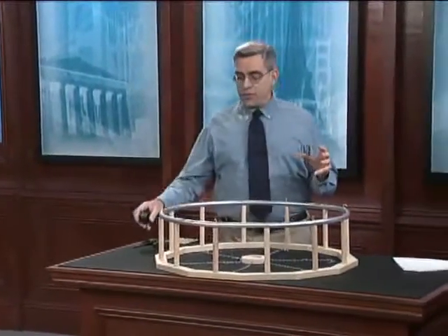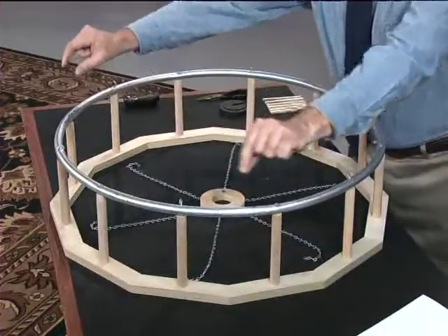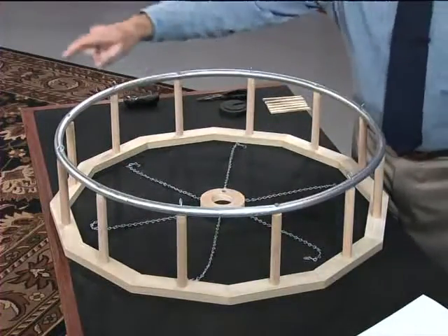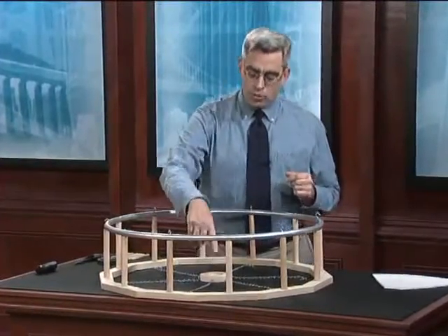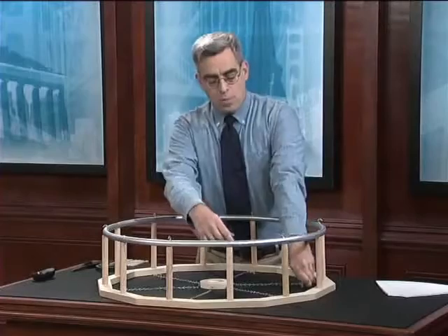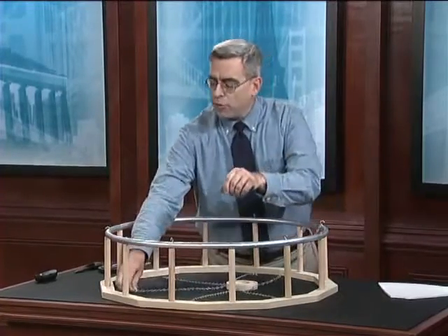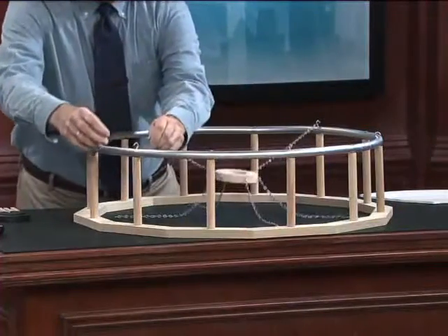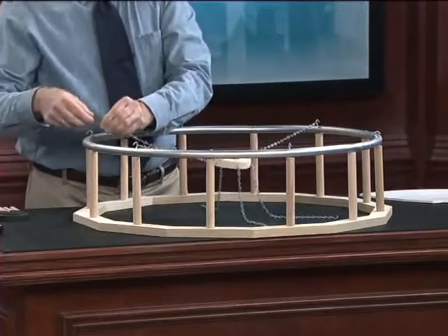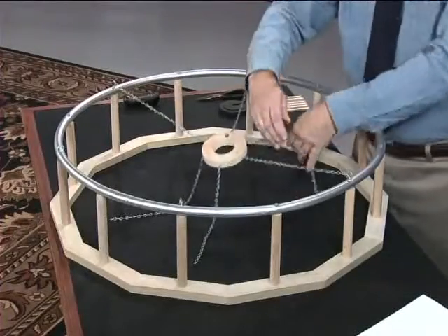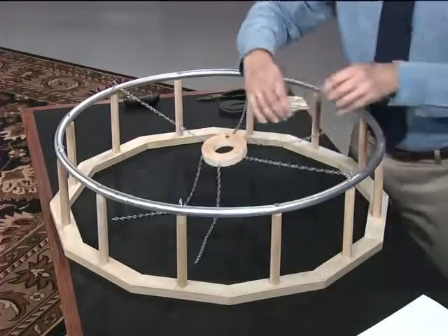Here you see a representation of the outer walls of Madison Square Garden. You see a ring located around the entire circumference of the building at the top of the structural columns. Down below we have another ring which is currently sitting on the floor of the arena, but we're going to raise it up by actually suspending it from a series of cables. And as you can see in my model, I'm using chains for these cables, just as I use chains for the various suspension bridge models that we've put together earlier in the course.